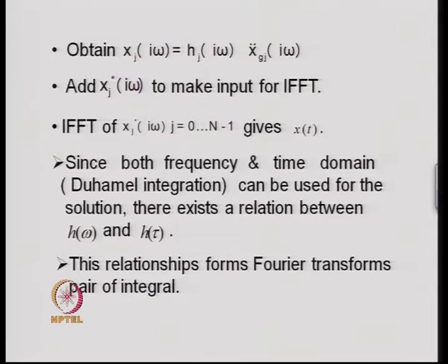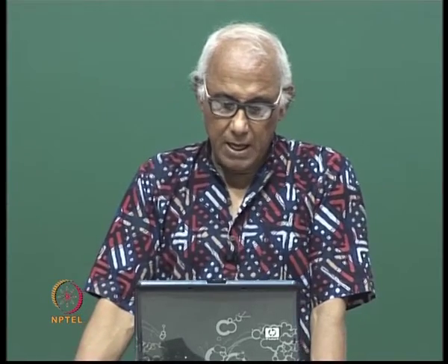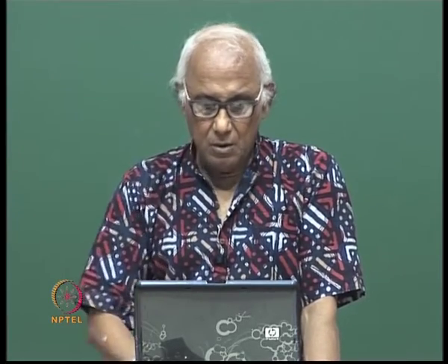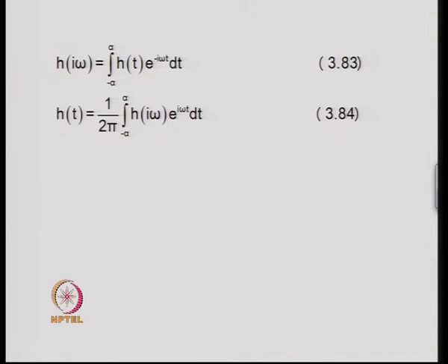Now, h tau specifically arises in the Duhamel integration, that is, for the unit impulse, the integration that we perform for obtaining the Duhamel integration is called h tau, and there exists a relationship between the frequency response function and h tau, and this relationship is nothing but again the Fourier pair of Fourier integral.